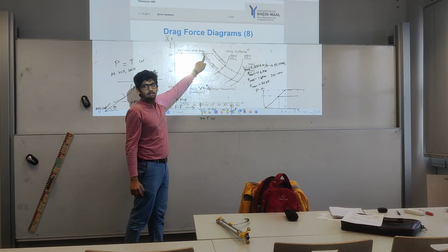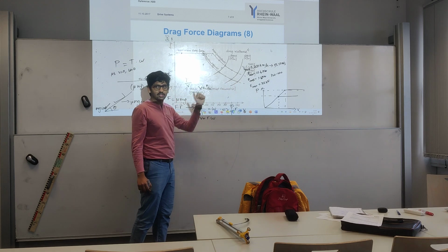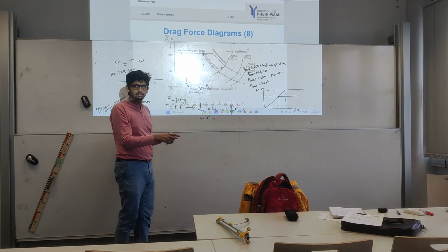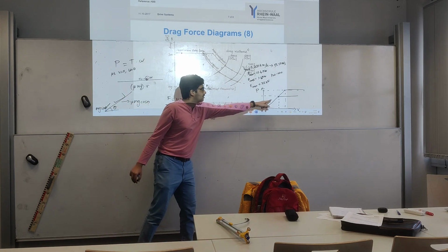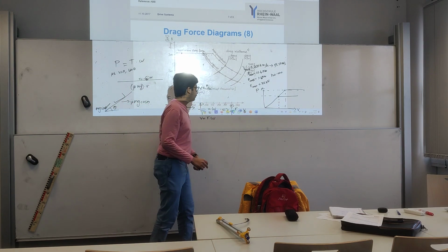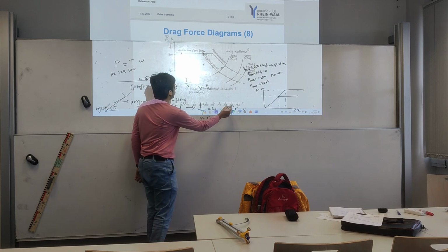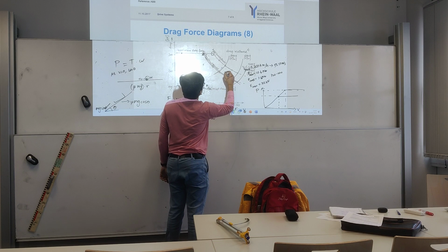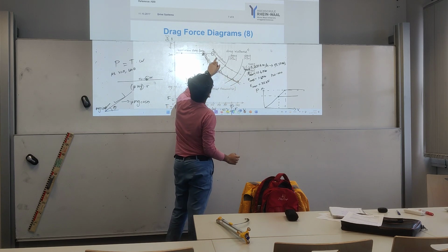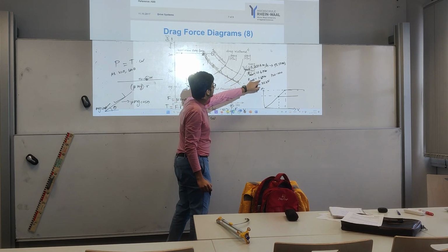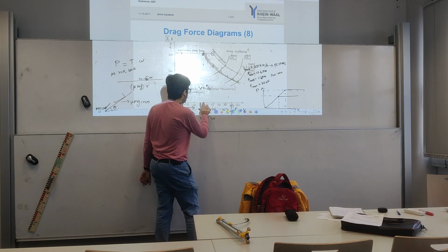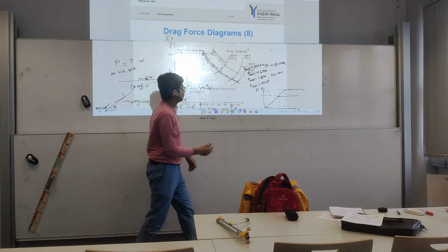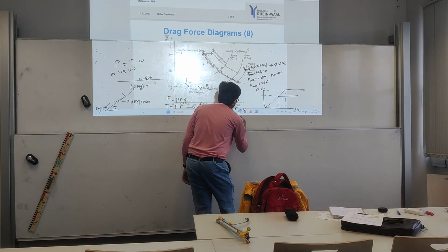Beyond this point, as the velocity increases, the torque is decreasing, because power is constant. Until then power was not constant, power was increasing like we saw here, but then it's becoming constant. This P I took was the maximum. Let's say we are drawing this line. I'm taking the maximum power line. So P max, I will take it as 10.4 megawatts. And in this case, the force is given directly, which is T by R. So what I would do would be this P divided by F.